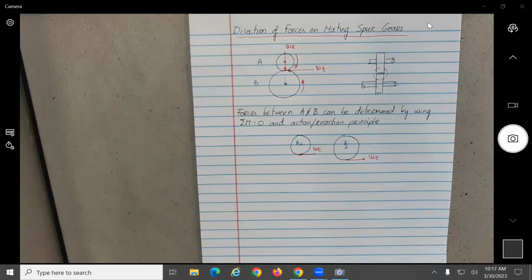Okay, so generally the advantage of the chain is that it will be able to transfer more power because we have less elongation. Okay, but also the other thing is that with some of these metal ones, if you have any misalignment, it might break more easily. The good thing of having a V-belt or something rubber is that if you don't have perfect alignment, it's more forgiving. That's why I think you see more V-belts in custom bikes, no? All right, because you need a perfect alignment because chains are not good in strength laterally, no? All right.